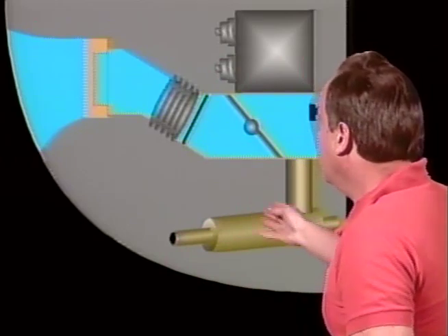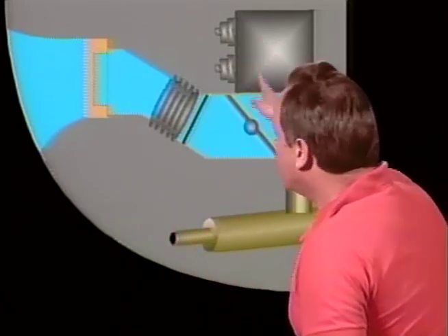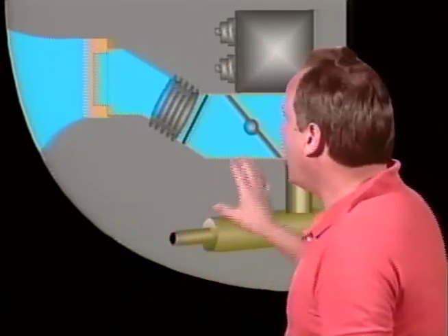In other words, some of the air going into the carburetor is hot air when you're trying to take off, and of course reduces the performance of the aircraft. Okay, so would you normally use a carburetor heater, preheater they call it, preheat for the carburetor on takeoff? And the answer is no, not unless it's absolutely necessary, because you do have loss of power when you have hot air going into the engine. The reason for that is the air is less dense. Also, the mixture gets a little richer because the air is less, the fuel stays the same, so the mixture gets richer. So a carburetor preheater is not generally used on takeoff.